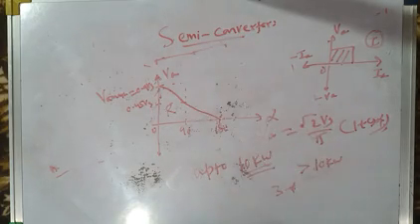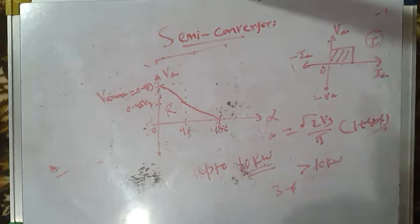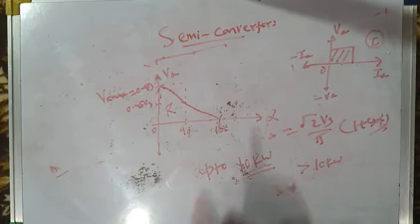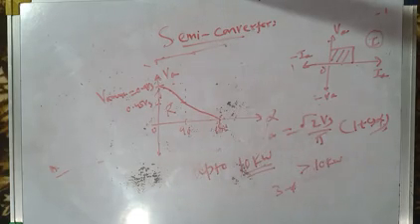Whereas on the other hand, a semi-converter operates only in first quadrant, that is as a rectifier in rectification mode only. Therefore, the DC motor drive fed from semiconverter, whether it is a single phase semiconverter or three-phase semiconverter, does not have capability of regeneration. It operates only in forward motoring mode, not in regeneration mode.